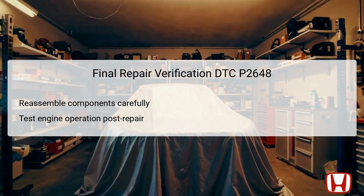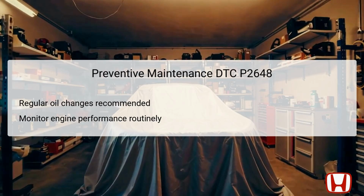enhances driver confidence. Preventive maintenance is critical in avoiding issues like DTC P2648 in the future. Regular oil changes are highly recommended, as clean oil is vital for proper solenoid operation and can significantly impact performance and longevity.